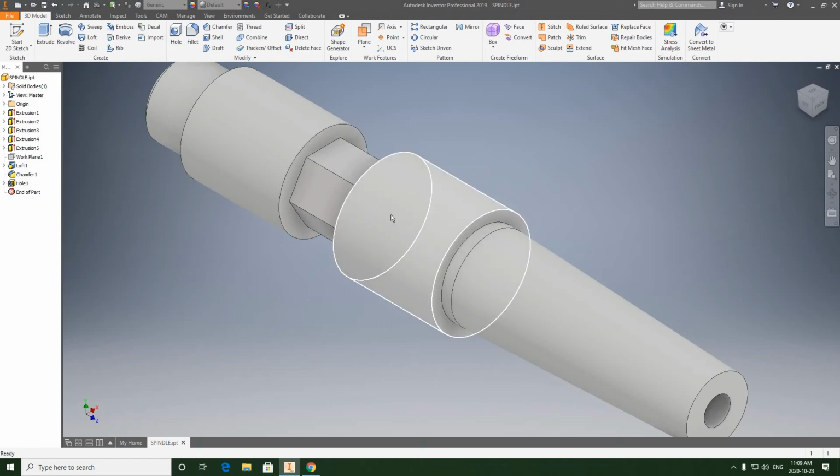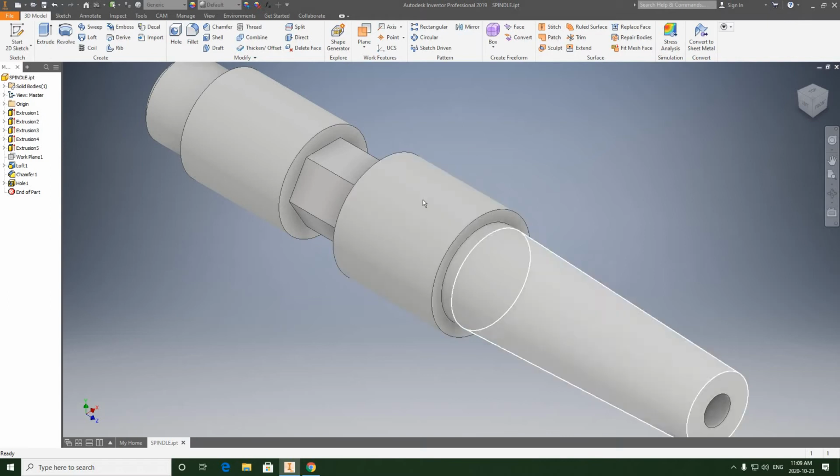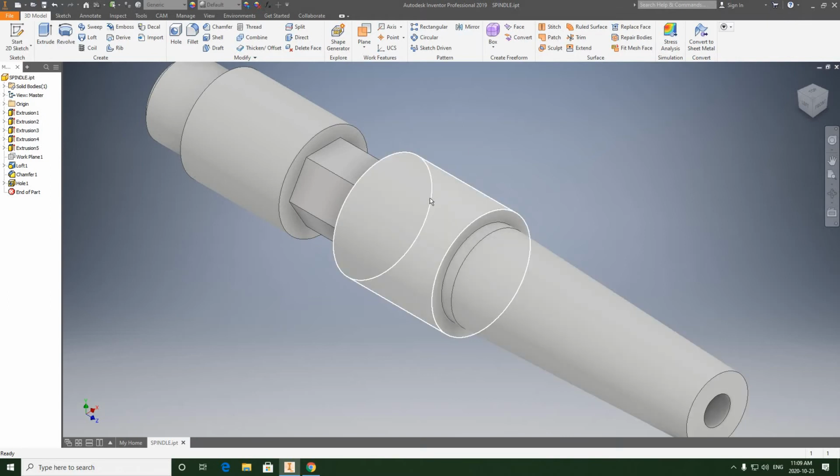So I'm basically starting with a solid 1 1/4 inch diameter of solid aluminum. That's this diameter right here. And we're going to activate the coil much like we would cut it on a lathe. So we're going to cut into it and we're going to extrude, cut material away to add the thread, much like a machinist would do it on a metal lathe.